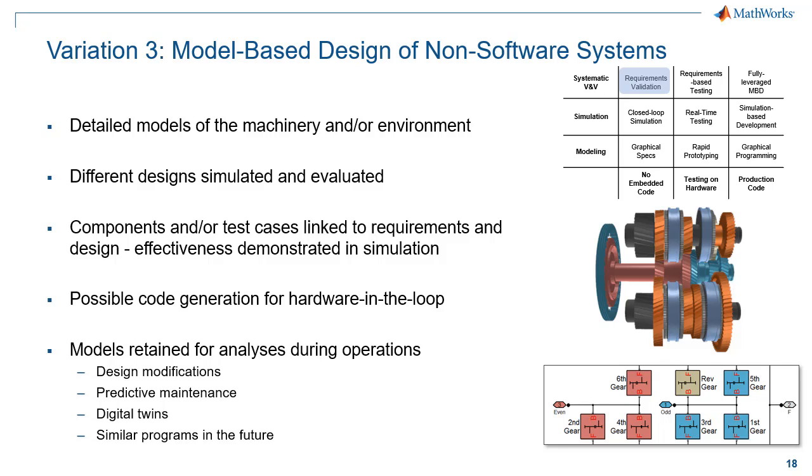The only reason you might generate code in this kind of workflow is you might do what I call a hardware in the loop test. And what I'm referring to here is the idea that you would take this high fidelity model you've built and convert it into code so that you can run it on a real-time operating system, which may interface with your pieces of hardware, or it may interface with the embedded software, the embedded system that was developed outside of Simulink. This is something that I did at my last job.